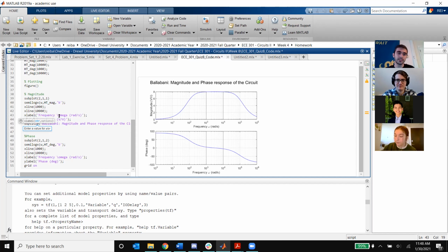So we do backslash, and this is an escape sequence in MATLAB. That's what it is called, backslash omega. And this is going to output the omega Greek letter. So we have it here. That's cool. You can do it with pi, with anything, right? I love how it looks, so I just make it.